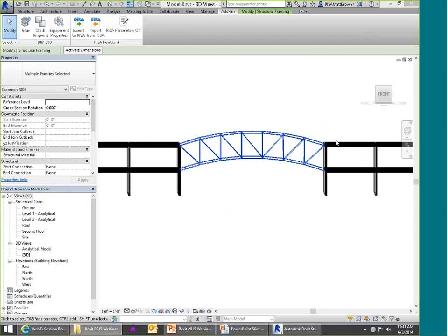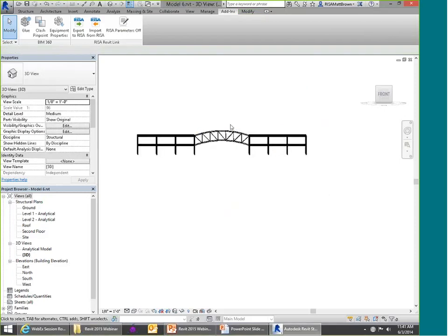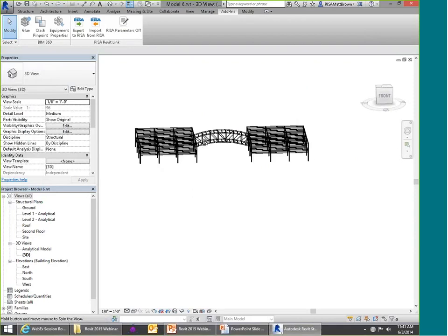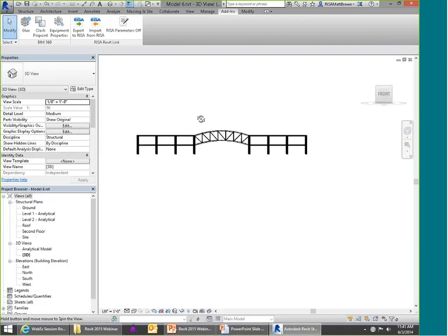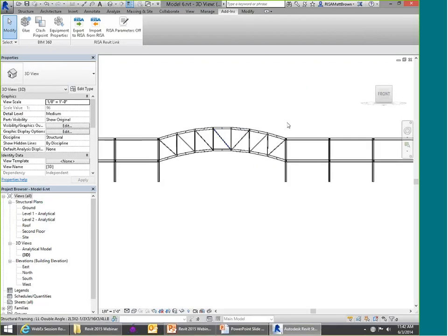So the point I'm trying to make here is that you can now do some sort of simultaneous workflow by using this export selected items only and carefully managing things, but you need to make sure that everybody coordinates with everyone else when you're making physical changes to the model, because those physical changes have to keep the entire model intact.